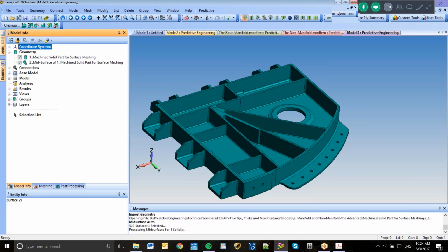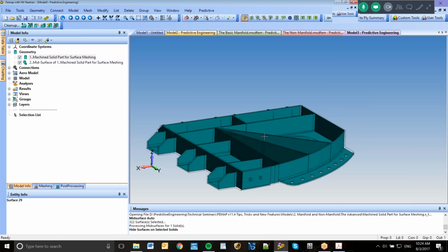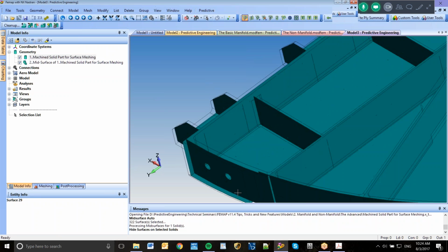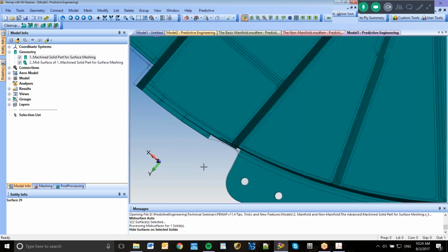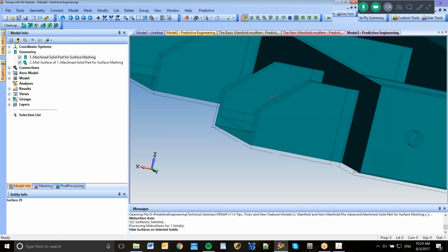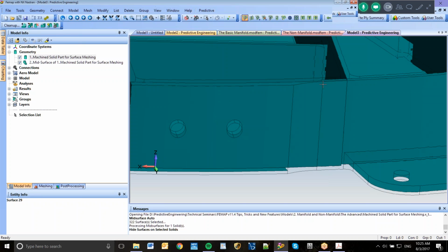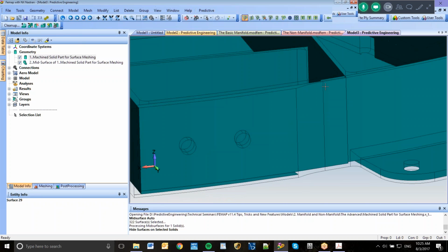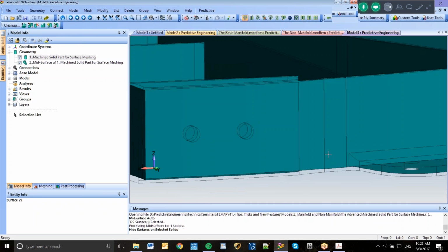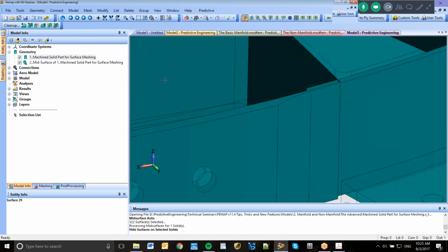And it goes through and sets it up, and I want to set this up to hide surfaces. And this is normal. This is what you'd expect to see, that you've got some gaps and overlaps and extra surfaces going on. And you notice how I can hold my cursor down and it zooms around that. That's one of the settings in preferences, zoom around cursor.